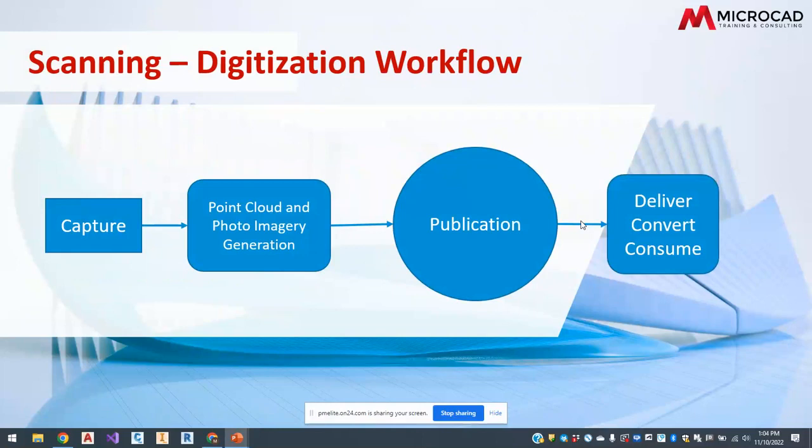Right? So we've done this conventionally with surveying methods. Land surveyors are typically the first ones we call for deed research and property boundaries, and then eventually topography and picking up utilities and so on. And for years, they've used conventional methods of total stations and collecting things by walking around and picking up the features of interest. So what scanning brings to that now is the ability to capture millions of points in a matter of minutes. And so you can see the efficiency right off the gate here that this brings.